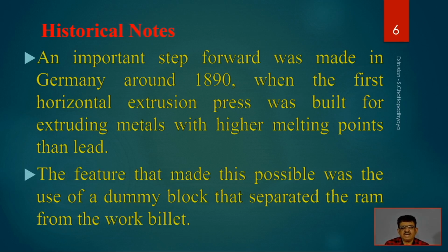And if the oxide comes into the product as a layer, the integrity of the product will be compromised. Because of the oxides, the frictional force will be more, so it will not be efficient. Many forces are there, and the entire thing becomes problematic so far as productivity is concerned, and also quality, because the surface oxide materials and scales will be extruded in the form of skin. So people came up with a dummy block.